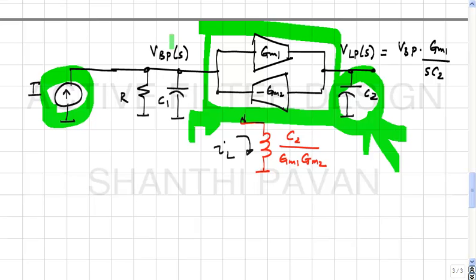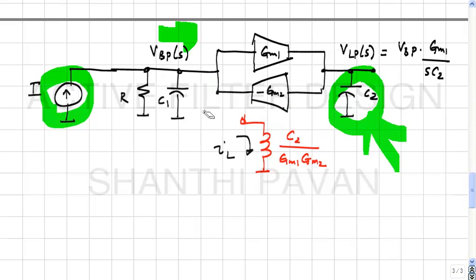So the current at port 1 will look like the voltage at port 2, and we know that looking into port 1 is an inductor. So the inductor current, which is the same as the port 1 current, must look like the port 2 voltage. Does that make sense? Okay.